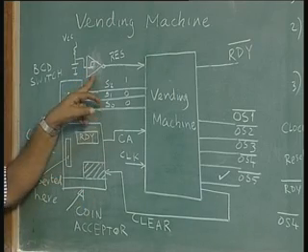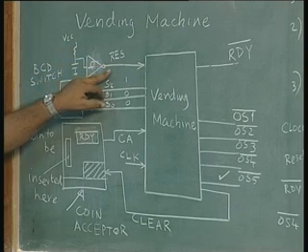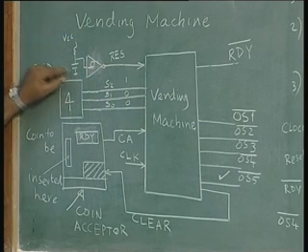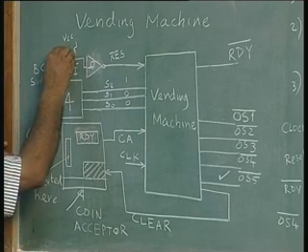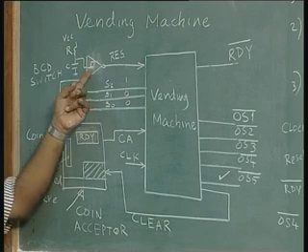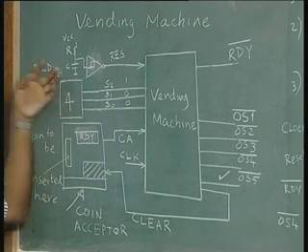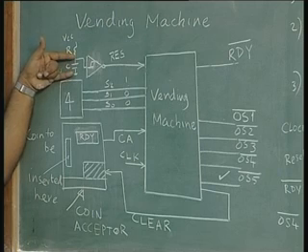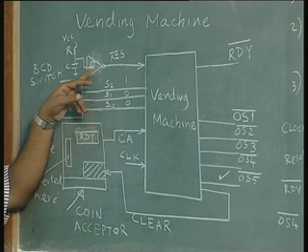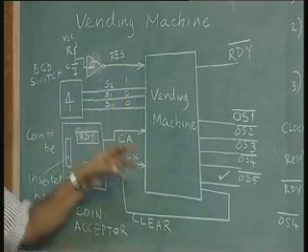The second thing is about the reset. We said the reset can be done once the power is switched on. It is actually a power-on reset. When the power is first switched on, there is this VCC and a capacitance, an RC circuit. The capacitance gets charged, but it takes a while. And this is a Schmitt trigger inverter, an inverting Schmitt trigger. So when the capacitor is not charged to a particular value, below the threshold value of the Schmitt trigger inverter, the input will be low and the output will be high. So that is the initial reset.